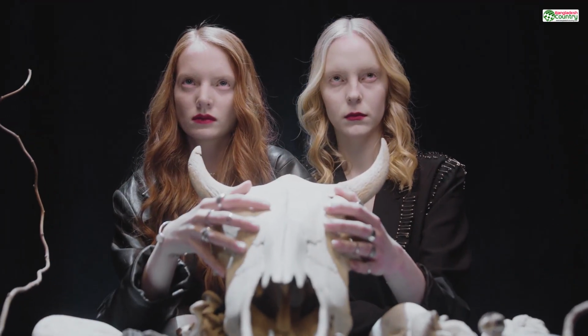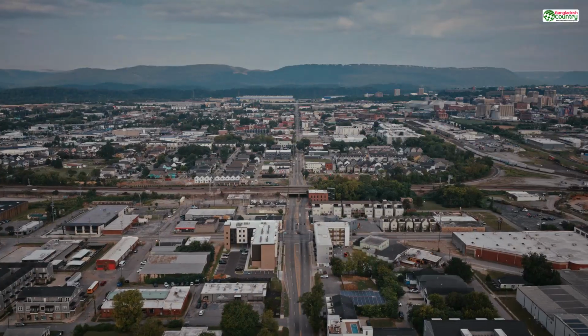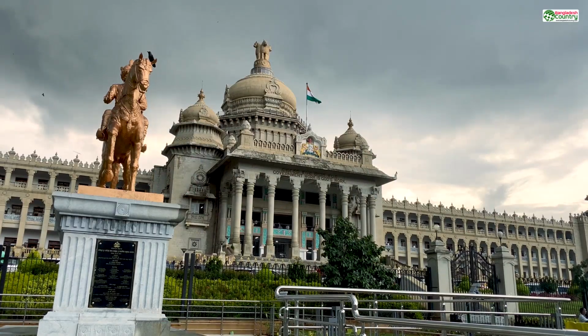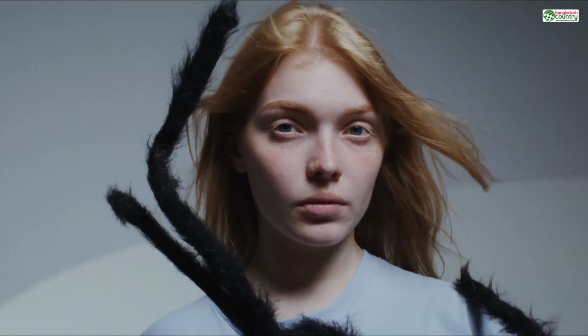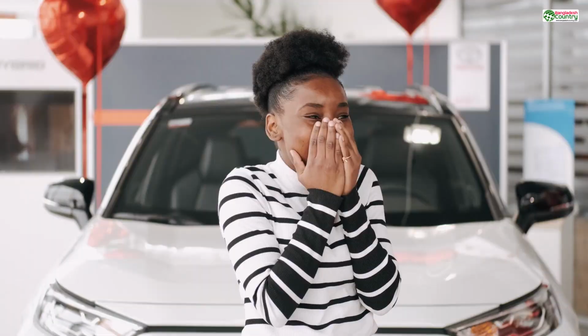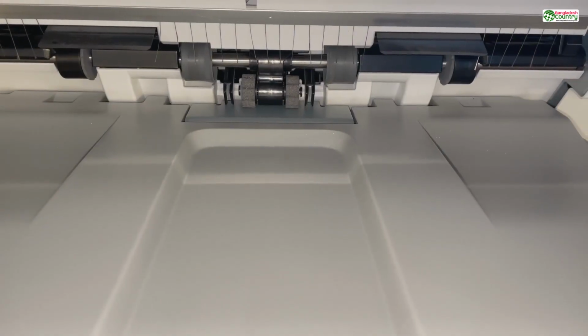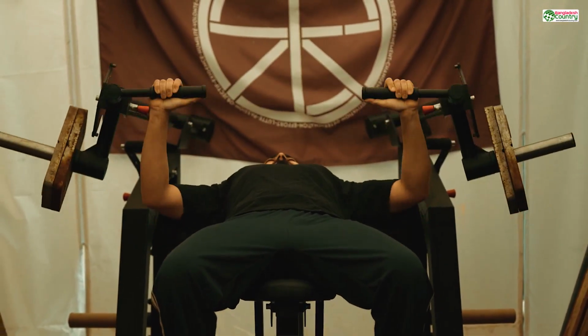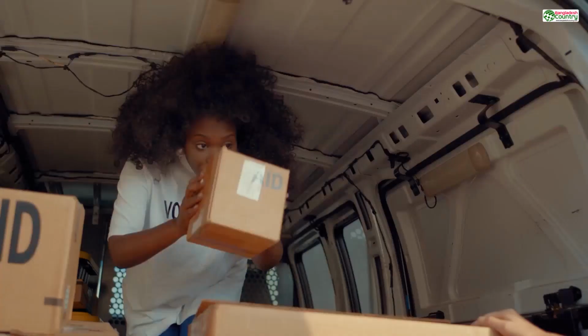We've now built the scaffolding on the outside to hold our model up during its creation. But what about the inside? If you were to pick up a professionally 3D printed part, you might be surprised by how light it is. That's because it's probably not a solid block of plastic. Printing a solid object is incredibly slow, expensive, and in most cases completely unnecessary. The real secret to creating parts that are both strong and lightweight lies within the model itself, in a hidden, internal geometric world that gives the object its strength and structure. This world is called infill, and that's where we're going next.